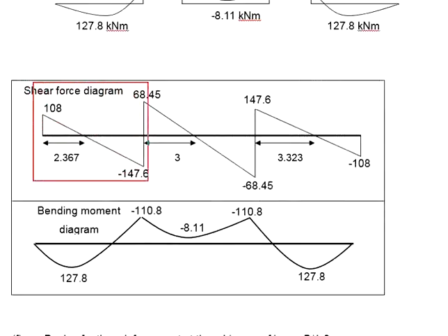This can be seen from the shear force diagram. For a typical beam, the maximum shear normally happens at the end of the beam, and towards the midspan the shear load reduces. When you design a beam for shear resistance based on the maximum shear load, and you choose to apply the shear link throughout the beam, of course the entire beam will pass in shear. Just that at the middle part of the beam, you do not really require that much shear reinforcement, since the shear load is relatively small.